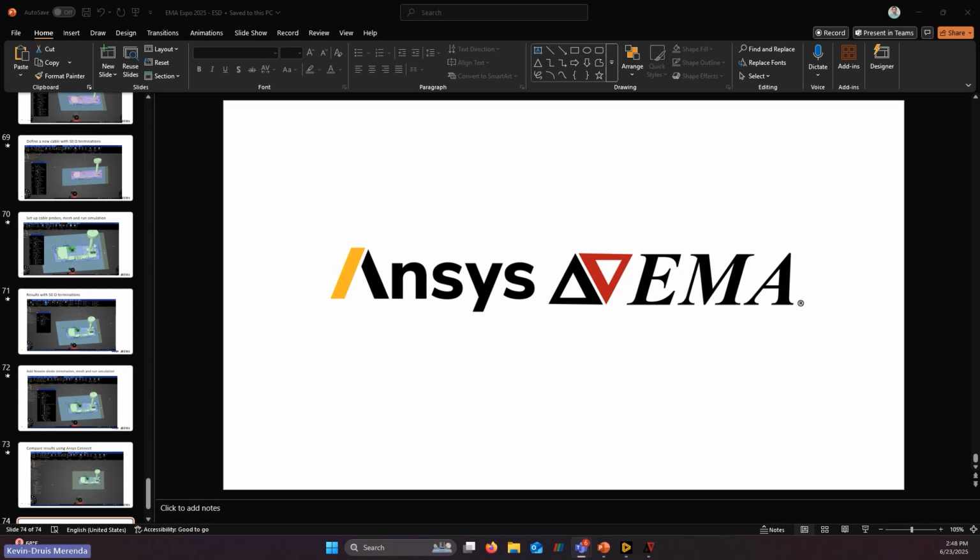The FDTD is in the EMA3D tab, and that is going to be using the nonlinear air chemistry model. So it's very focused on modeling air discharges. If you want to model anything else than an air discharge, then you have to go to the time domain FEM solver in the Charge tab.